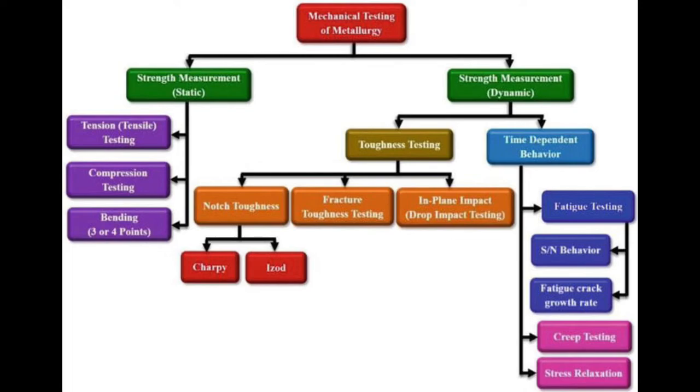In standard Charpy V-notch testing, a 10 by 10 mm square bar has a small V-shaped notch machined on the face. The hammer, swung from a large pendulum, will strike the side opposite the notch. If the metal does not break, the level of energy is increased until the metal breaks. The Izod pivoting arm is raised to a specific height, or constant potential energy, and then released. The arm swings down, hitting the notched sample, breaking the specimen.